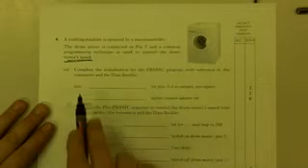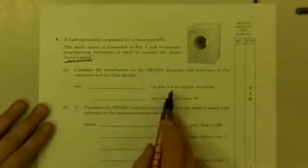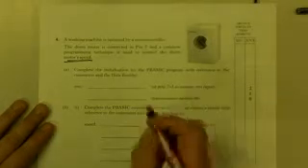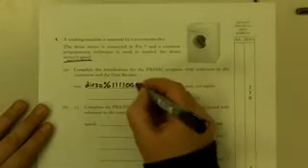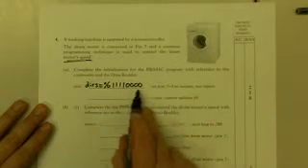Right, well, in order to initiate the direction of information register, whether or not we're setting them up as inputs or outputs, we need to put the command dirs equals percentage and then 4 ones, which represent the outputs, and 4 zeros that represent the input pins.